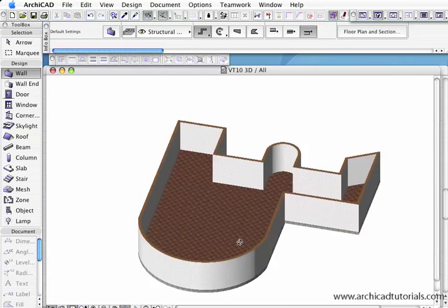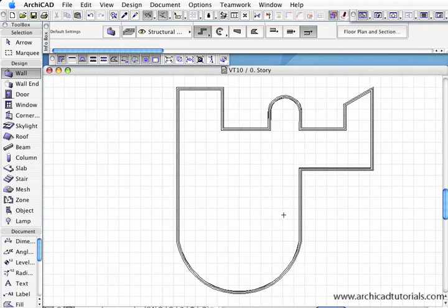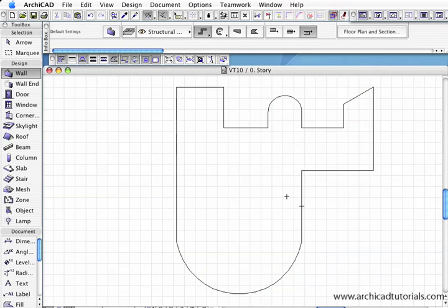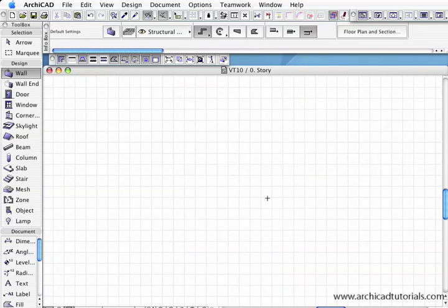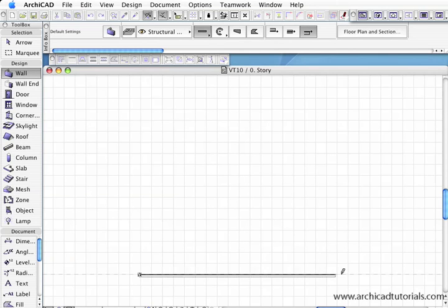That's the result. I'm just going to close it off again. Editing walls. I'm going to go Control A and delete all the walls again. In fact, I don't want the slab anymore either. So I'm just going to draw a straight wall and holding the Shift key down to constrain it this time. I'm going to click the tracker again.